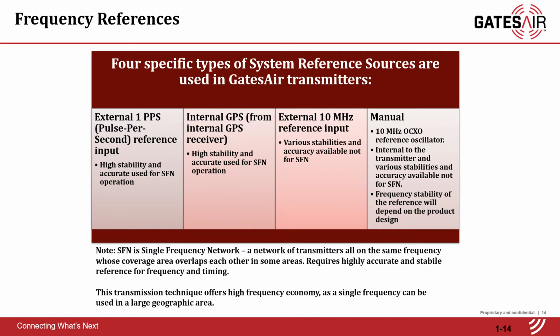There are several different reference frequencies used as clock pulses for the operation of equipment. Two are using global satellite sources. One is 1 PPS, which typically will come from a GPS receiver, or some equipment has built-in GPS receivers, so all you do is hook up a GPS antenna to it. Both of these are highly accurate and can be used to synchronize transmitters in different locations, since the source is coming from a common satellite.